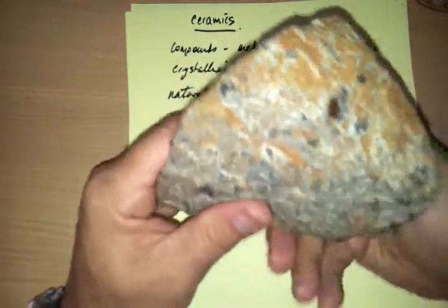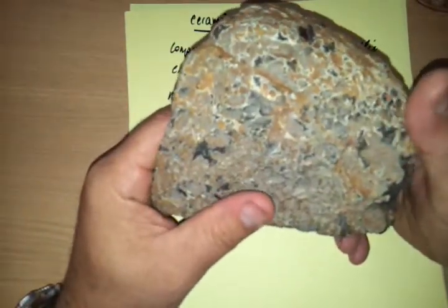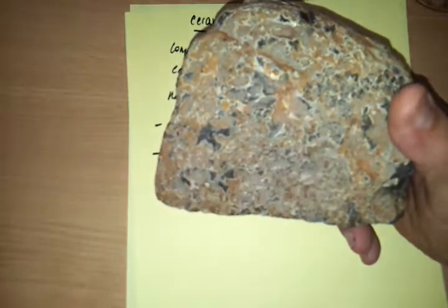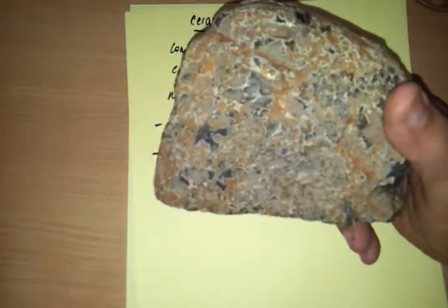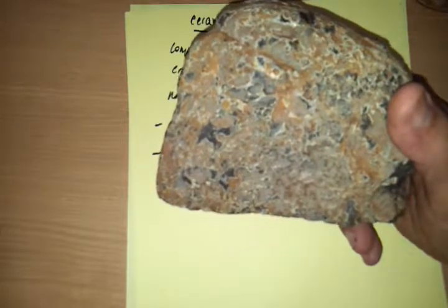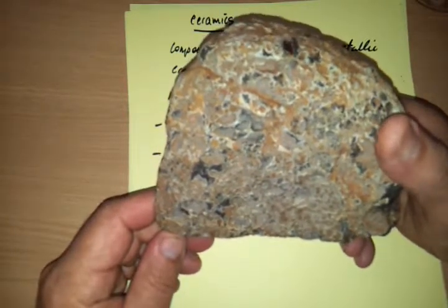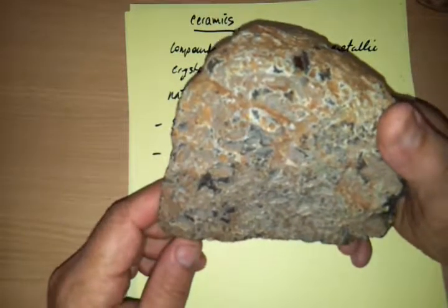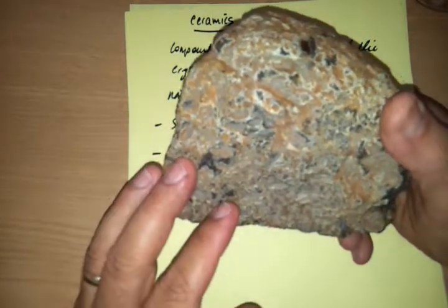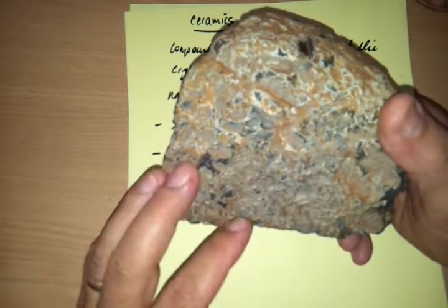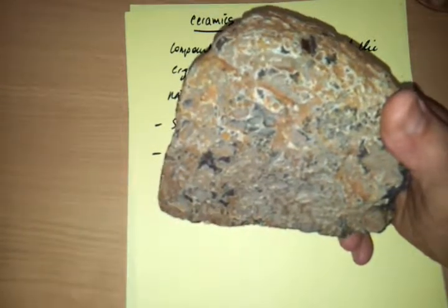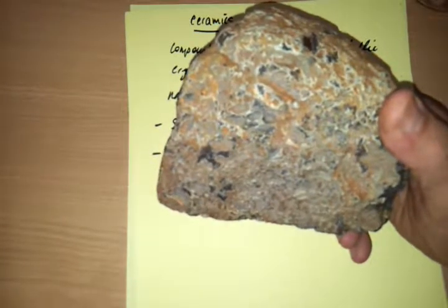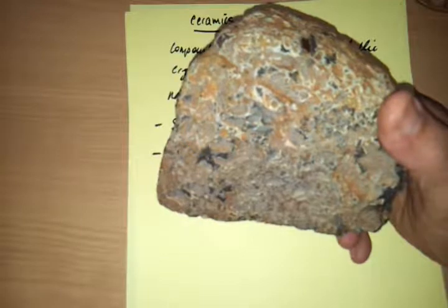But igneous rocks are very dense, produced from cooling lava, and typical examples are obsidian, bluestone, or basalt, and they're very often used in the building industry. Very difficult to shape, unlike sedimentary rocks, but they are very hard wearing, so they're great for use in road and hard wearing surfaces like road bases. They're also used extensively in building structures, but again, difficult to work.